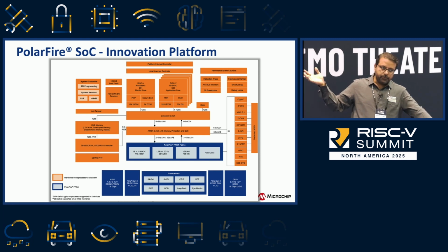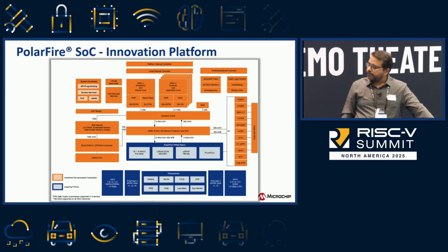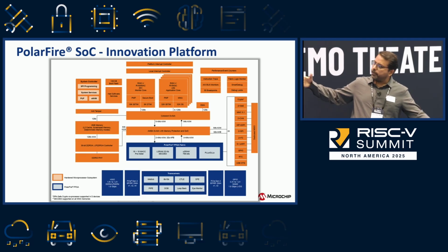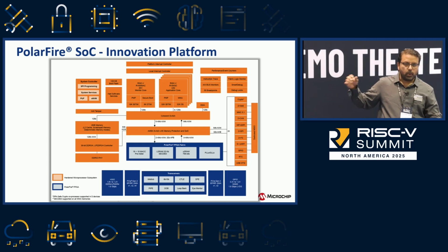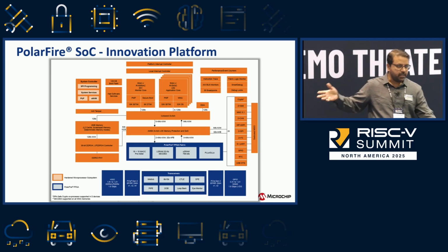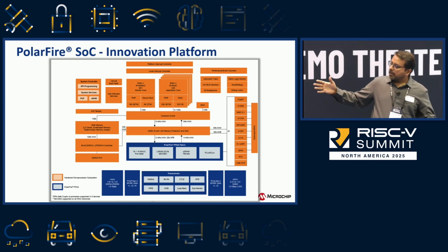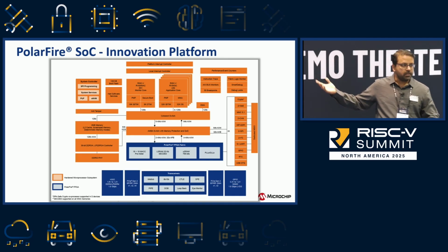It has the 5 RISC-V processor cores, the caches, the DDR controllers, and a host of peripheral IPs that you can communicate with. All right? If you're an FPGA developer, the blue bits are the ones you may be interested in. That's the FPGA fabric, the 1.6 gig fast I/O and 12.7 gig transceivers, PCIe interface, and so on. All right? There is an AMBA bus or AXI bus that connects these two within the chip.